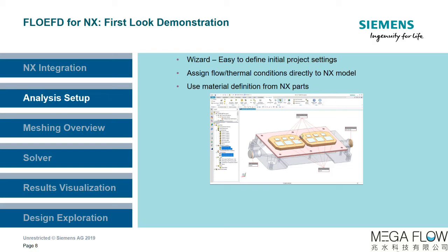Now we have prepared and checked the geometry, we're ready to set up an analysis on the assembly. The FloEFD project is created using a wizard-driven process. Flow and thermal boundary conditions are applied directly onto the NX parts. If materials have been applied in NX, these can be imported directly into the FloEFD engineering database.